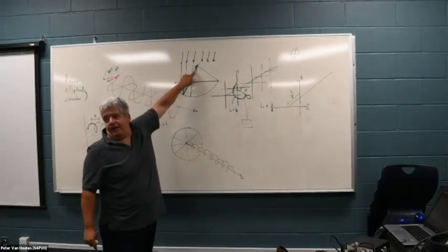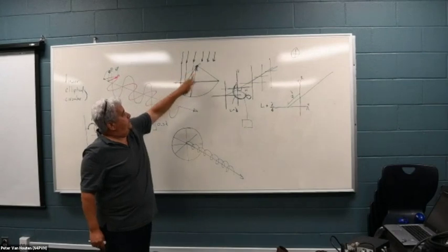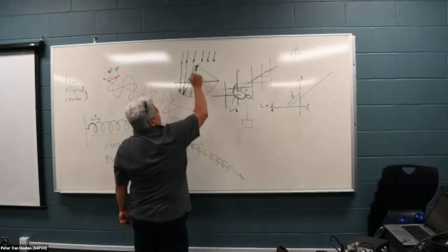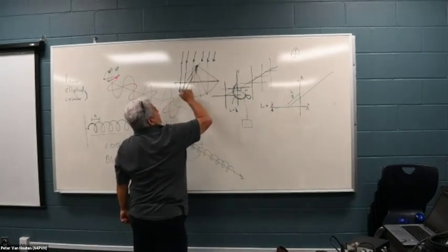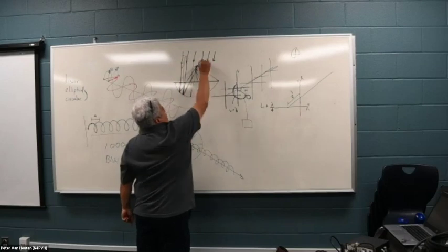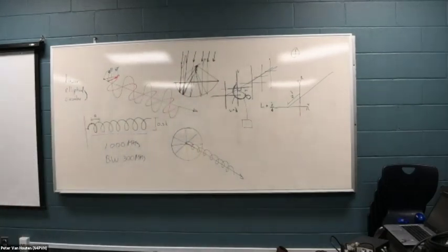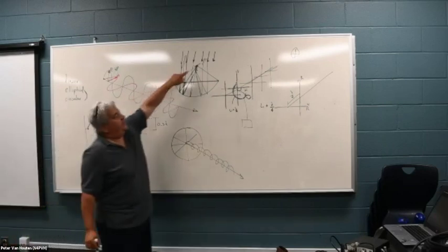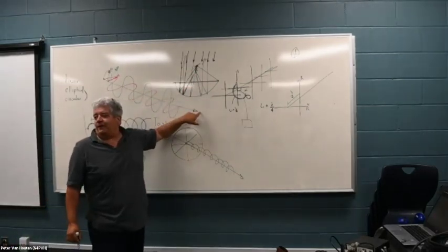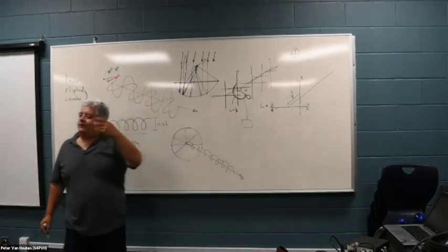Circular polarization, right-hand. But this is going to transmit in this direction, and then go out. Okay? What happens to my right-hand circular polarization? It has bounced from some place. It turns the other way. So I'm emitting with a right-hand circular polarization helix, but as soon as it bounces here, it's going to go the other way.